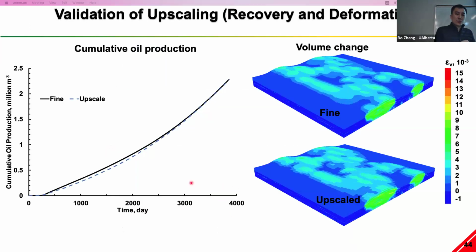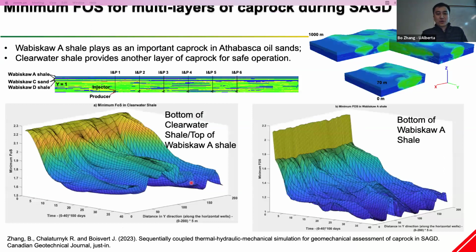So then it is also possible for us to match the cumulative oil production and volume change between the fine scale and upscale models. What is really important is that we can actually use this upscaling technique to now dive into the research of the caprock integrity during SAGD.